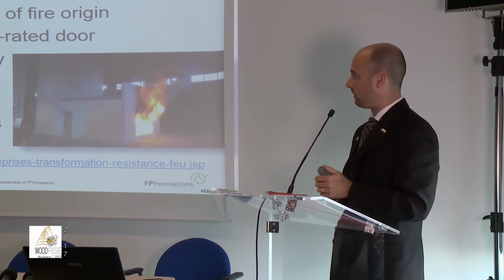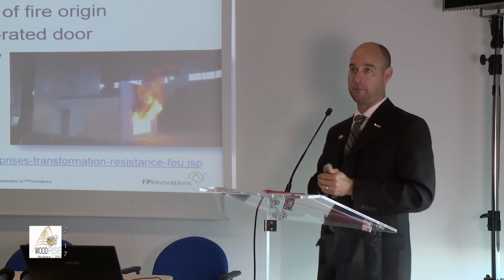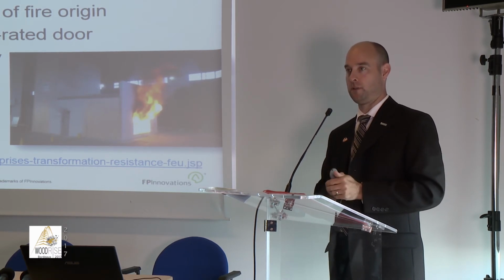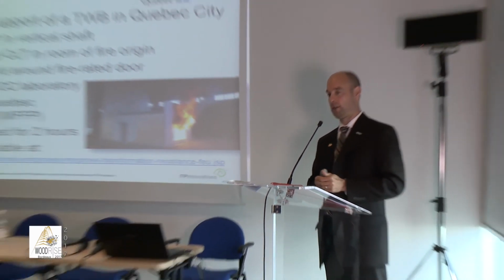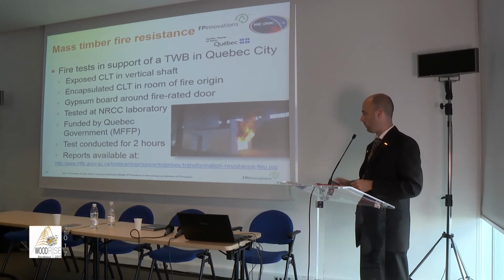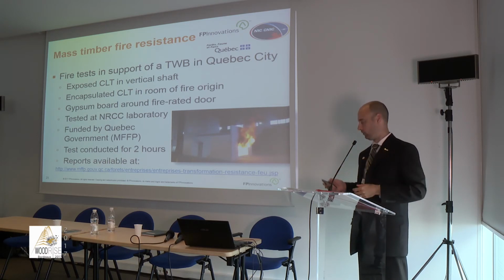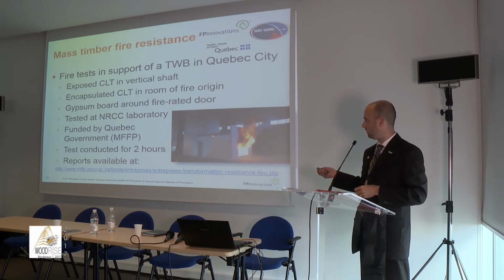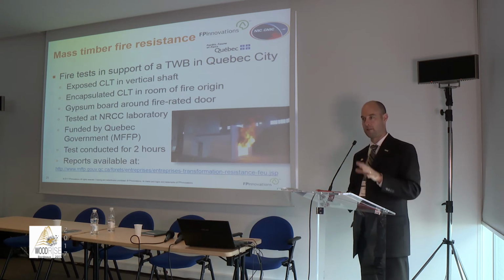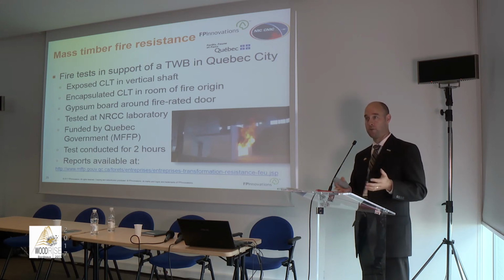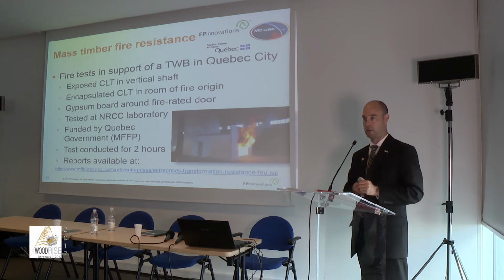Obviously, we're in the context of tall wood buildings. This is one of the full-scale tests that we conducted in support of the 13-story building in Quebec City. We went from component basis to the full system basis. So we tested the wall assemblies and the ceiling assembly in the furnace test, the standard fire resistance test. And obviously it was new, it's 13-story, we're way beyond what the prescriptive code is permitting.